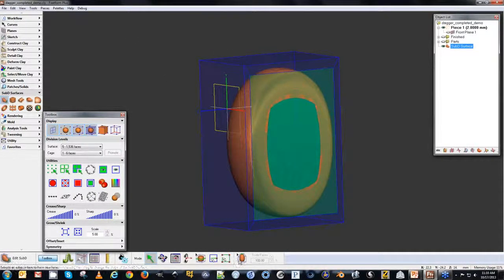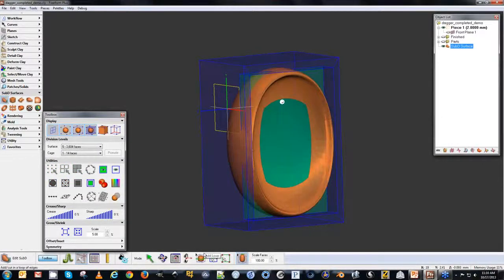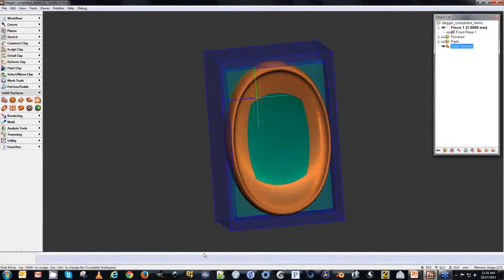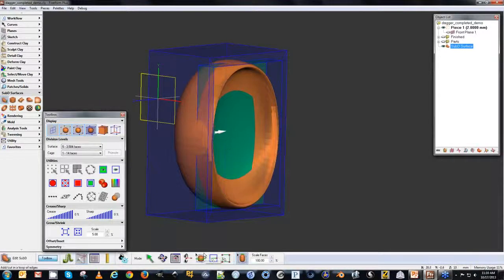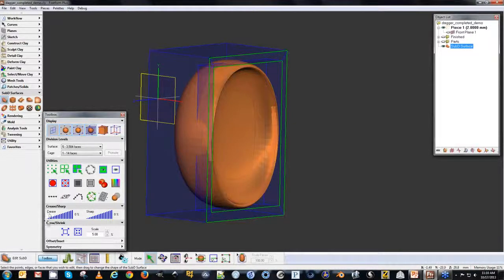And now I'm going to extrude this face inward. Clicking extrude, I then touch the face and push in with my haptic device. Now I've created new geometry, and you can see that it's a very rounded edge. That's not going to work very well for this sword handle, so I'm going to go back into my selection tool and select a loop, which is this area right here, as well as the outside loop. Holding Control and selecting the loop again, I'm going to crease this edge to sharpen it up.